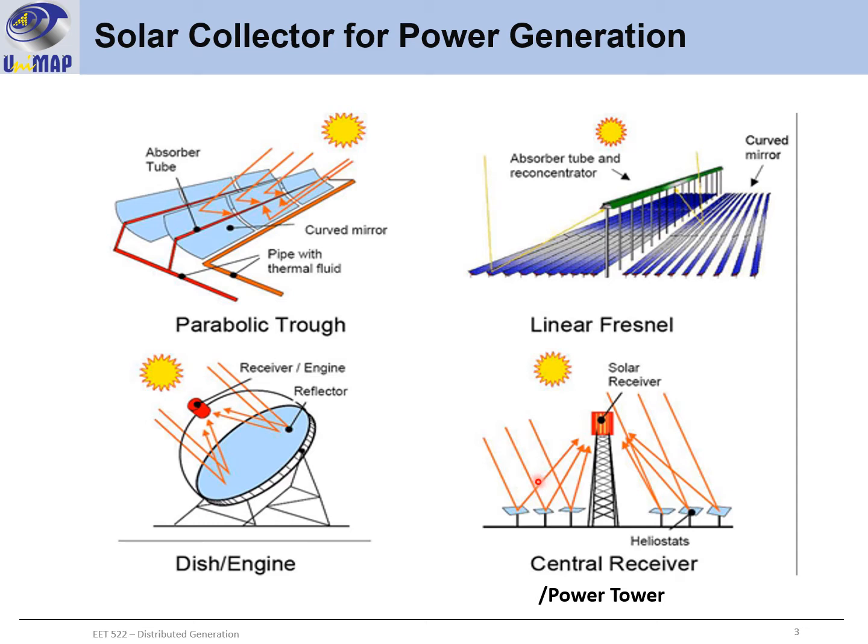The last one is the technology that uses the concept of central receiver, or the power tower. In this concept, you will have a solar tower in the middle, and then you will have a lot of heliostats, as we call them, the mirrors that will be pointed to the center, to the top of the tower, and it will heat up the molten salt inside this storage. This will be used to power up the turbine by producing steam. We will go through each of these technologies in this lecture.